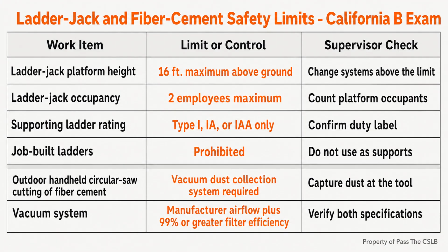Before cladding covers the wall, I check the water-resistive barrier laps and the flashing sequence. The upper layer goes over the lower layer. Horizontal laps are at least 2 inches. Vertical joints are at least 6 inches. Flashing remains continuous where required, including above projecting wood trim.